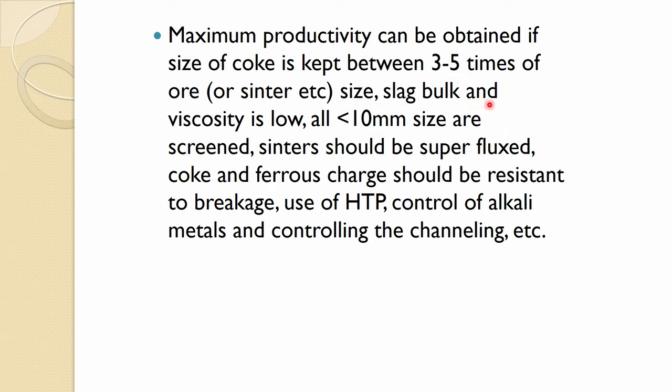Slag bulk and viscosity are low, all less than 10 millimeter size are screened, and sinters should be superfluxed, so there is less slag volume. Coke and ferrous charge in the superflux also reduce the cohesive zone and delay the melting temperature, so it is increased. So, that is one good thing.